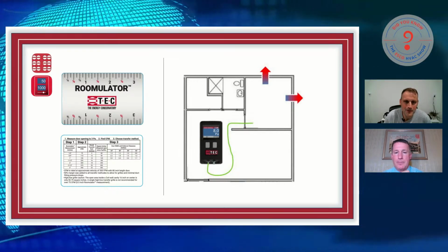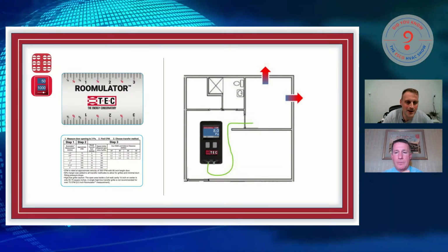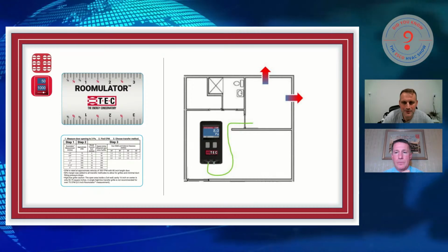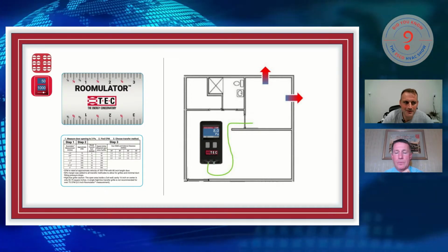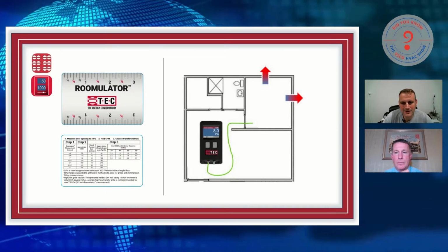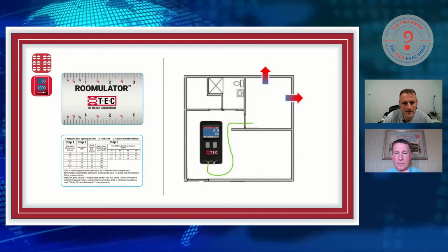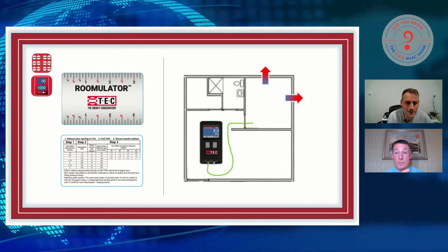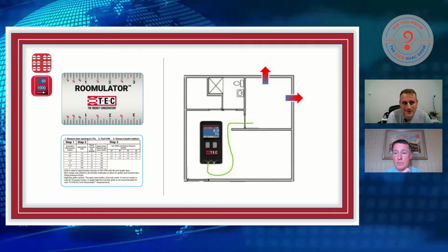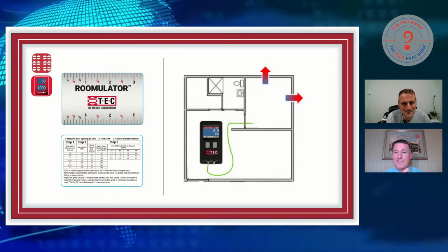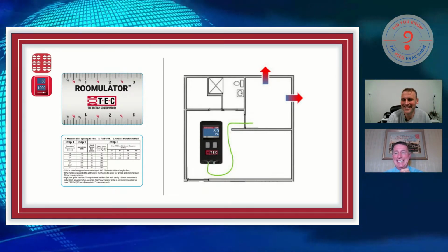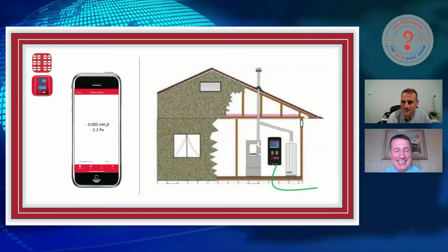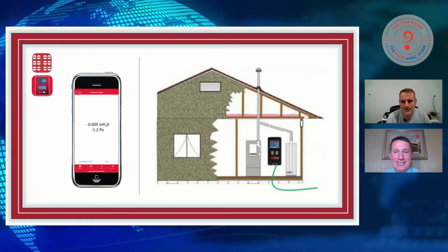So when you figure out what size drop you're going to do, you don't have to worry about, I've got these grills, does it matter? There's enough fluff built into the measurements to absorb it. So don't worry about it. Just trust the card and it'll get you there. And if you come in under 3 and you're at 2 pascals, so be it. That's even better. That's a handy little tool. I like that. But you need a micromanometer to get that measurement.